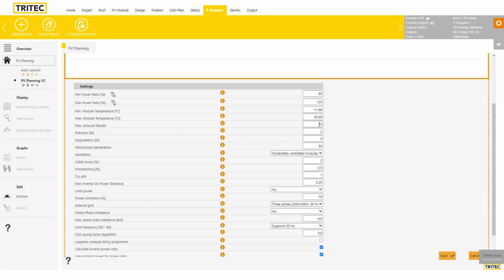Well, maybe I do the explanation right now. We try to do the sorting so that the variations use as few inverters as possible, because you don't want to end up with 10 inverters if you could do the same with, let's say, 1 or 2. It's probably more expensive to have more inverters, even if they are smaller in dimension. Maybe there are also more failures in the system, and certainly more time is needed to mount them and connect the modules to them.